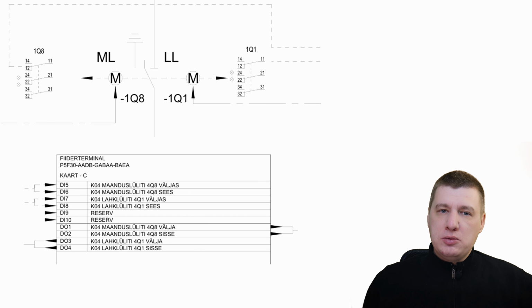The relay is programmed so you cannot close the earth switch 1Q8 while the circuit breaker 1Q0 is closed. We also define the phase rotation, usually 1 to 3 or ABC, which is mandatory for the electrical protection functions like ANSI 67 and 67N to work correctly.